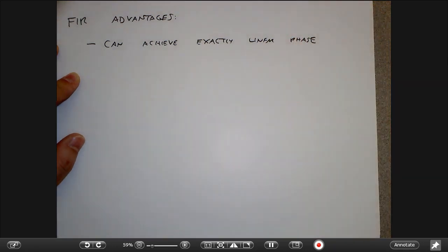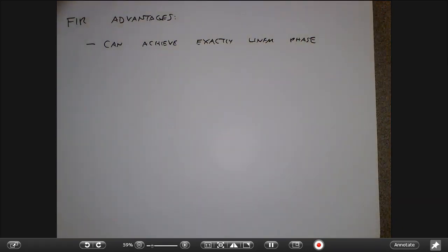And we showed that linear phase filters have this nice symmetric impulse response, right? You can't do that with IIR filters because IIR filters are infinitely long, right? That means that there is no middle point for an IIR filter that you can get symmetry around. And that means that IIR filters necessarily have some sort of phase distortion that you may have to deal with.